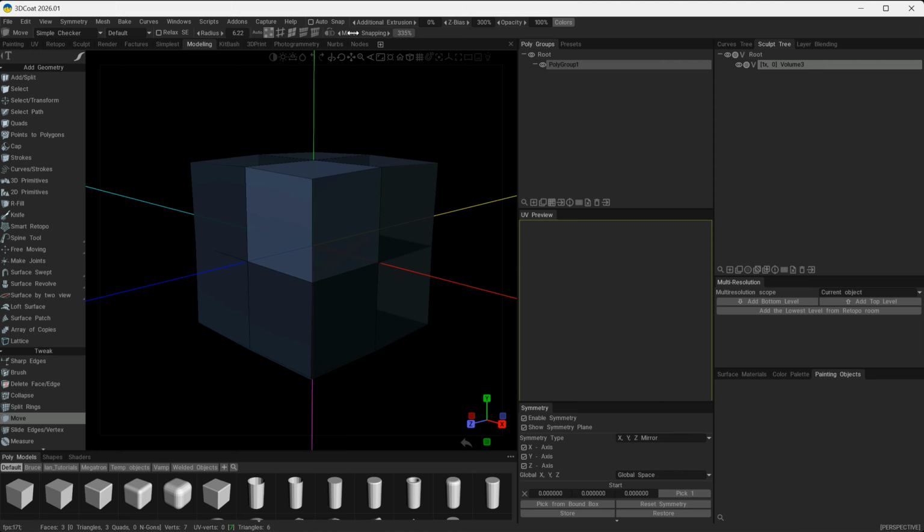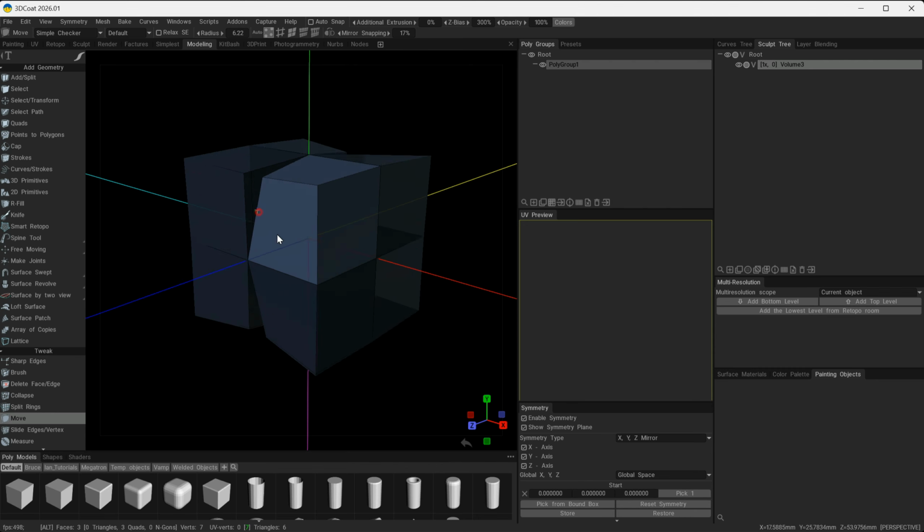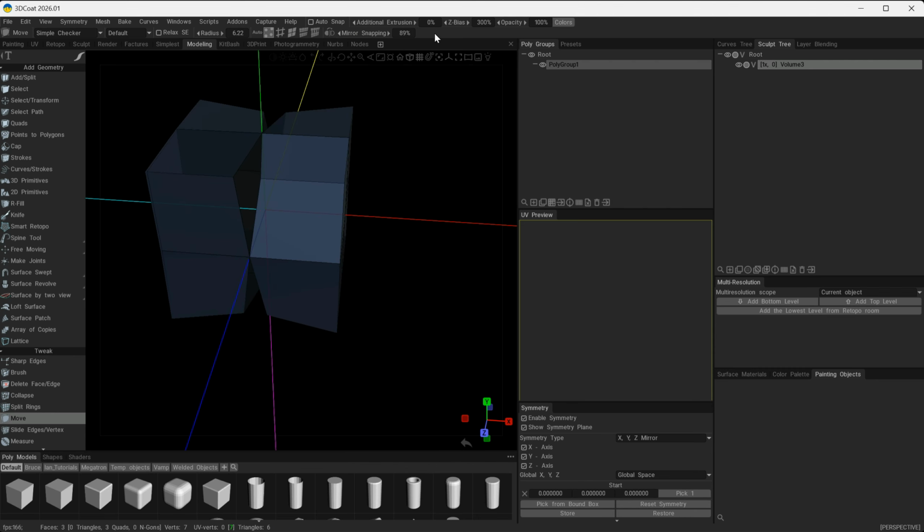So first of all, you'll notice my snapping, mirror snapping, is set to quite a high value. If I move this down, let's say over here, and I take this vertex here and move it, you can see it pulls away from the mirror quite easily. If I increase the snapping on here, then it will snap a lot sooner, and it's a little bit more difficult to pull that away from the initial snapping. And if I turn it right the way up, I've got to start pulling quite away before it pulls apart, and you can see it snaps quite a distance away.